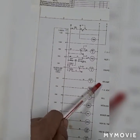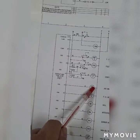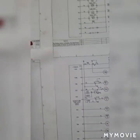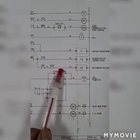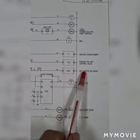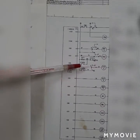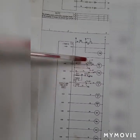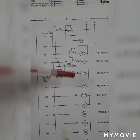It gives a signal to the air damper solenoid valve to close the air damper for about 2 seconds, and then after 2 seconds this air damper solenoid will be de-energized again to feed air inside the furnace, after the fire has been built inside of my burner.